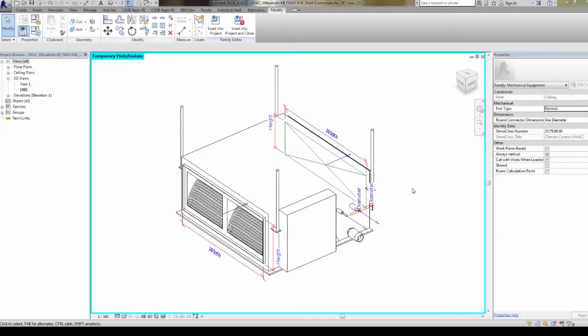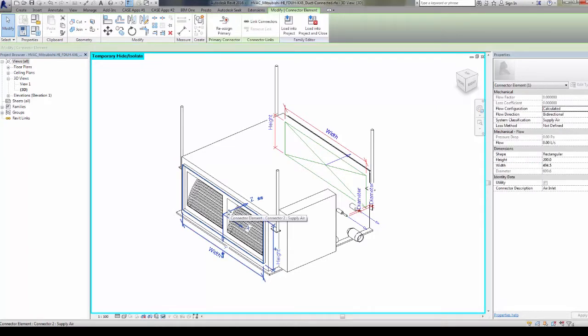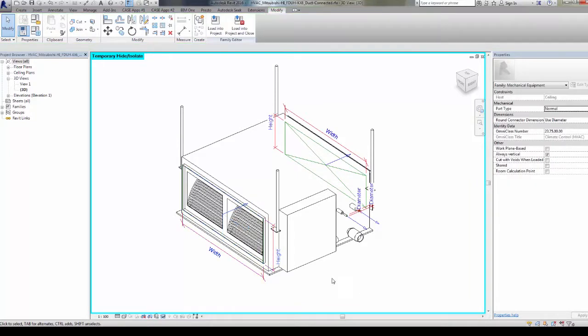For the example that is being treated, we are making the following consideration. The BIM families of indoor units from manufacturers that we have found are very different, and some of them have been modeled in a better way than others. Then, we are facing situations such as this example, where the links are incorrectly connected. In this case, the link is oriented inwards, so this indoor unit could not be connected since it could mean that the duct is placed inside the indoor unit.